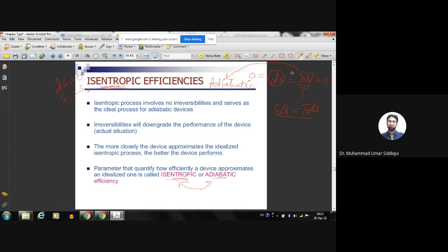This energy loss is actually coming from the electrical energy provided to the motor. So in real life, the motor will not be isentropic. All of the electrical energy will not be converted into work output, but some of it will always be rejected as heat because of the friction within the motor, because of the irreversibilities in the motor.